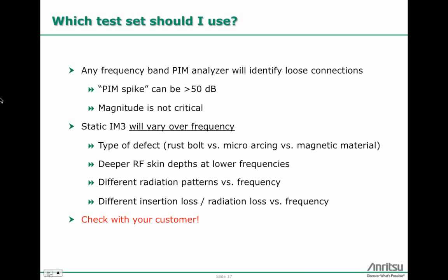I also, when I'm radiating through an antenna, the radiation patterns out of that antenna are going to be different versus frequency, and it comes down to the electrical length of that antenna. A good example is an indoor antenna where, let's say, for example, I have a small indoor antenna. The back plane on the back of that antenna is some number of wavelengths at the high frequency.